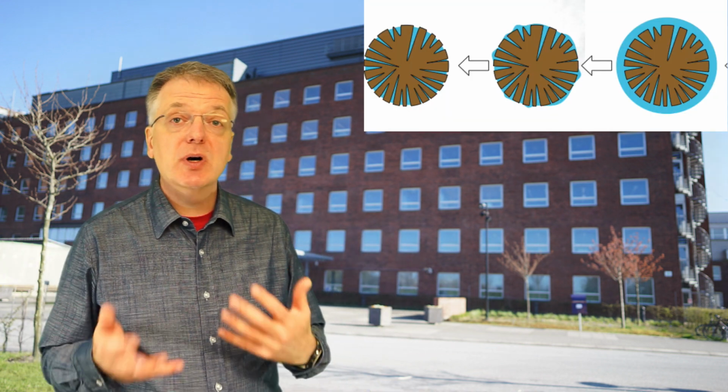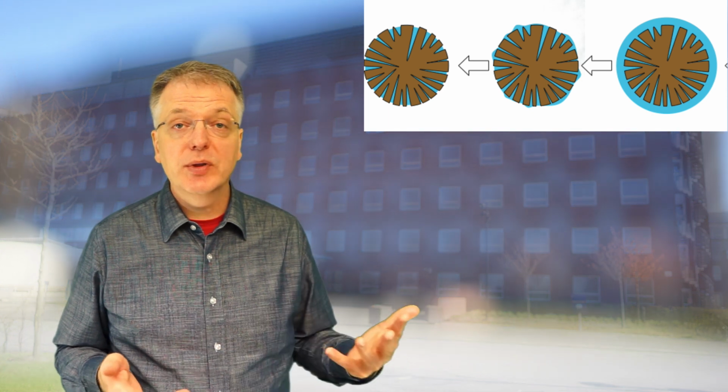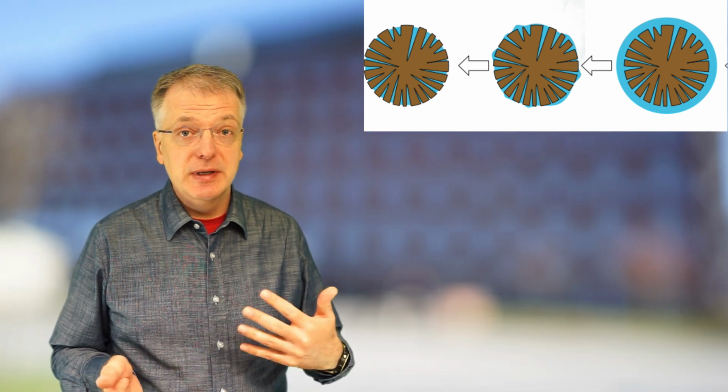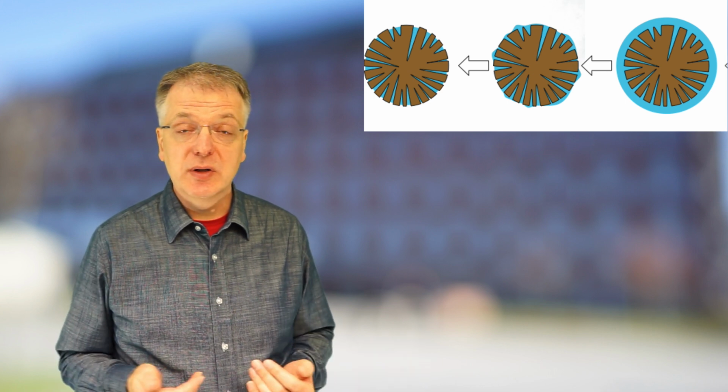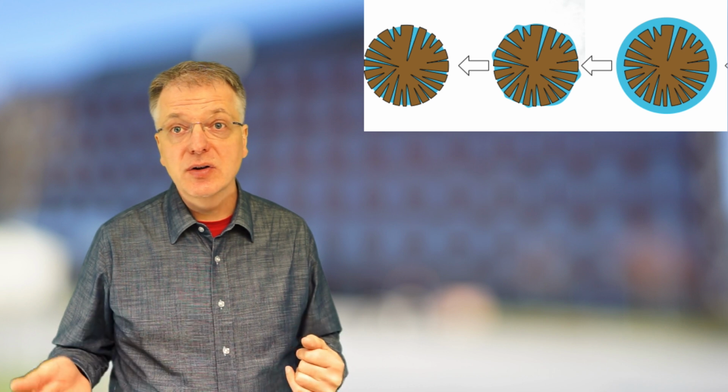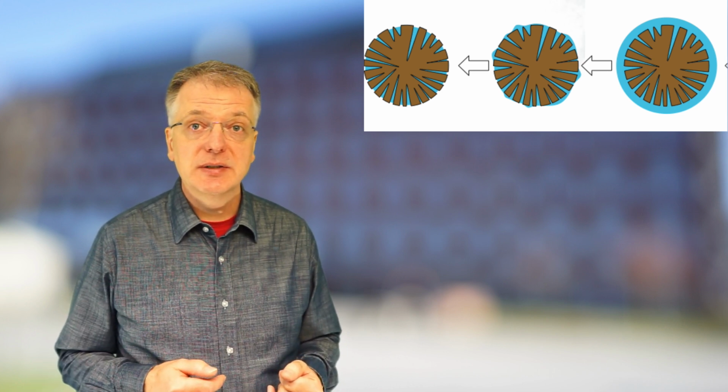The drying rate develops a bit differently during the drying process depending on if the drying goods is hygroscopic or non-hygroscopic. If we start with the surface wet material, both kinds of material behave in the same way initially. The air we dry with is in essence only in contact with water. Since the surface of the water remains essentially constant, so does the drying rate.